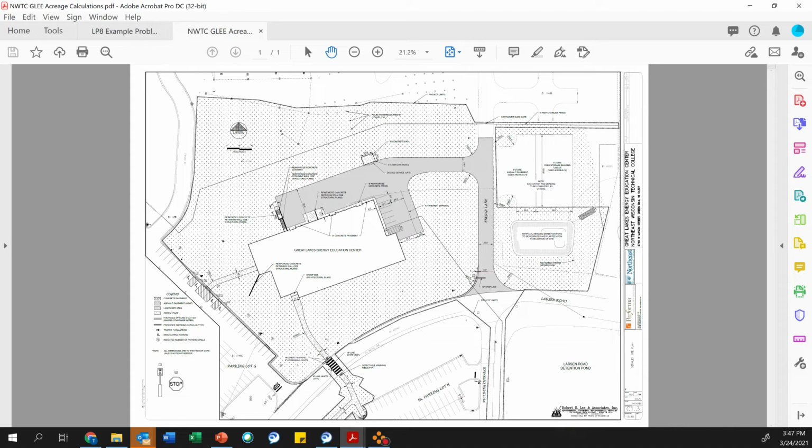So you can kind of see the project limits here. They're figuring out all of this water that hits the surface at some time will run into that artificial wetland detention pond. Okay, so now time of concentration, right? How long does it take water that hits there to get to there, etc. If there's a ditch, a culvert, obviously there's probably a culvert over this drive. So there's a time of concentration that is a complicated mess. But typically what we can do is the storm duration can be our time of concentration.